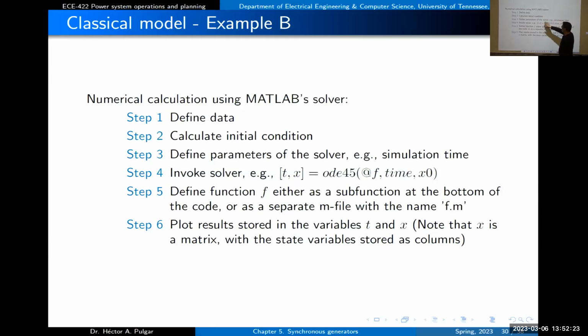And then we need to define the parameters of the solver. So there are some parameters, like the maximum time step we will take in the solver. We didn't use it last time, but we can specify that if we want. Another parameter we need to define has to do with the time. What is the window of time in which we're going to have this simulation?